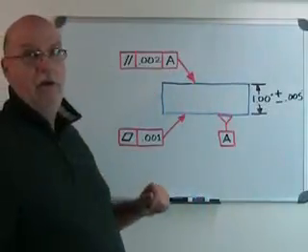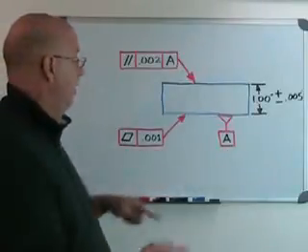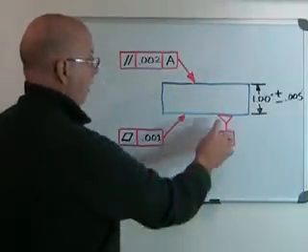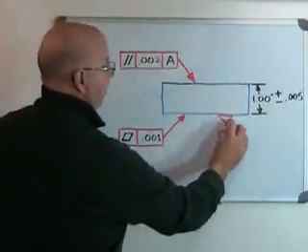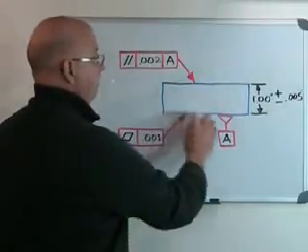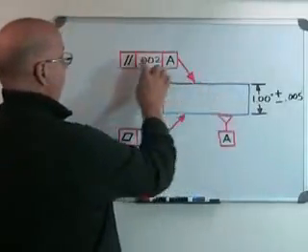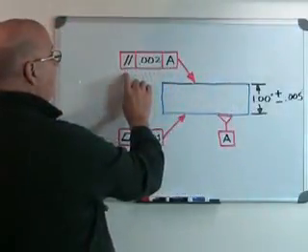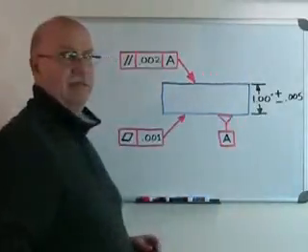And the A here relates to the datum A, or if you prefer, reference A. So this lower surface, the one that is touched by the red triangle here, that's usually black. I'm just putting colors here to make things a little more visible. But this surface here, the one that touches the red triangle and that's marked as A, is my datum A, or my A reference surface. And that means that when I read up here the callout, this means that this surface here must be parallel to within 2/1000ths of an inch to that datum surface A.